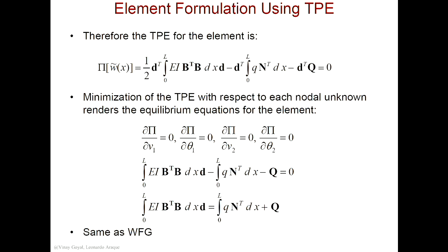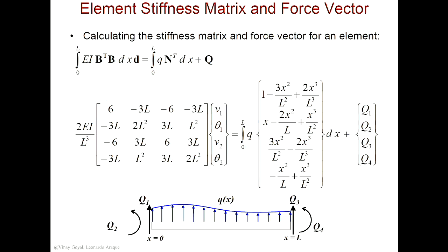Okay. All right. So now that I have this done, why not just plug this into Mathematica? I know B already, B transpose, I know B. Plug it in, just let Mathematica do the integrals for you. And you can basically get the answer to the problem. So the stiffness matrix for a single element, the local element stiffness matrix, looks like this.